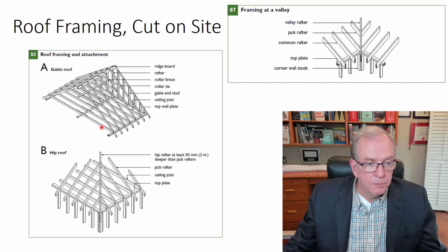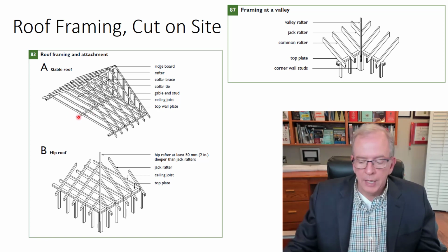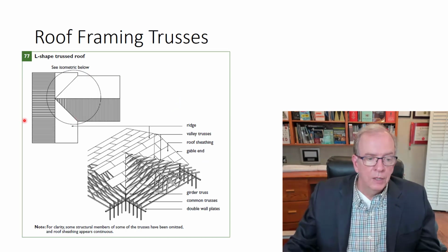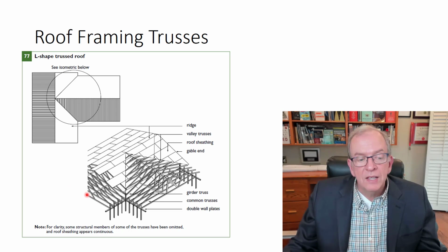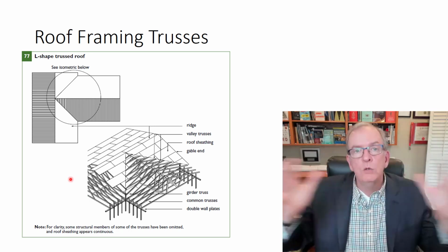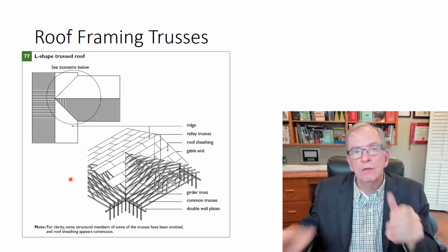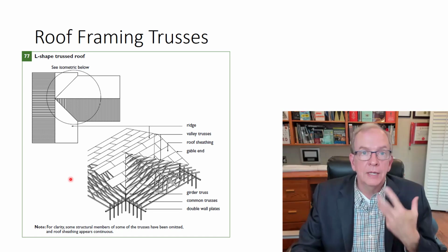Ceiling joists, in this particular case, will lap over and then they rest on a bearing wall. That wall becomes a bearing wall. With a truss roof, the bottom chord, in most cases, will be non-load bearing, meaning that it doesn't require a load bearing wall underneath it. So that's a big advantage. You can span really wide distances without having to have a load bearing wall underneath it. Can you imagine that?